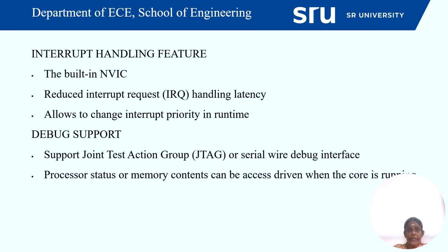And then the interrupt handling feature. We already saw that the NVIC is specifically for handling interrupts. The built-in NVIC reduces the interrupt request handling latency. As we said about latency, once an interrupt occurs, it should be responded to immediately by the processor. This is measured in terms of low latency, and it allows changing the interrupt priority